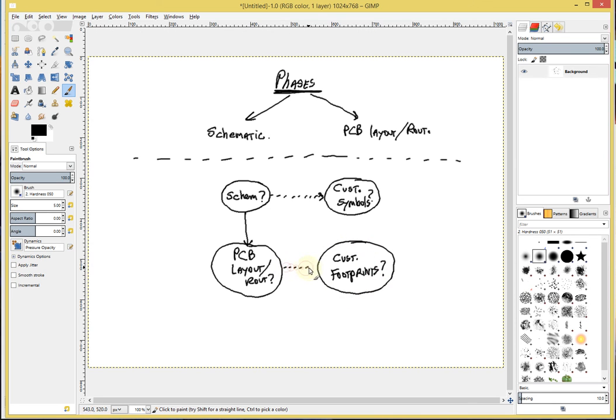Because when you're doing a PCB layout, it may be the case that a symbol on your schematic capture already comes equipped with a footprint, or comes with a library of footprints for common package types that you can apply to your schematic components. But a lot of times you may have to create your own custom footprints, and for that you need to know how to do that. This is usually part of the PCB layout, or it may be necessary to do in a separate package. In OrCAD, however, there's also a separate one. Let me show you before I do that.